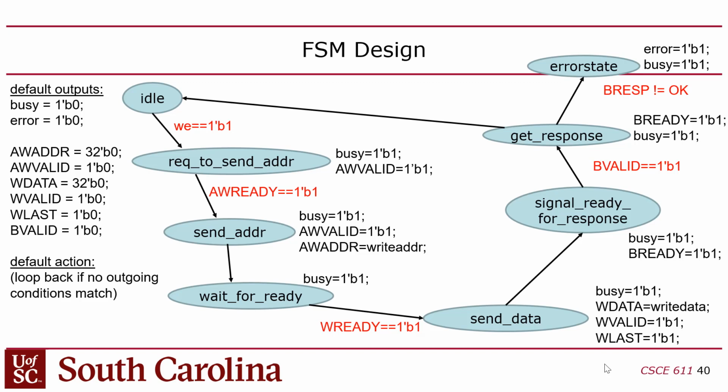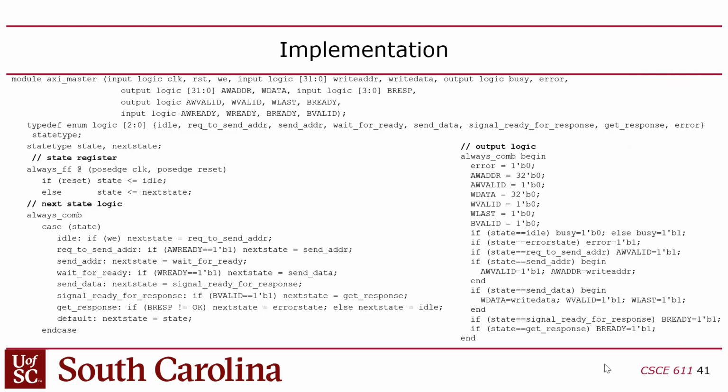Anyway, that's a more practical example. Okay, so then I put the implementation in here, and basically I split it. Again, I've got the enumerated type for the state. I've got the clock logic here, the next state logic here. The next state logic, in this case, I use a case statement. You can use a case statement instead of just an if then else. So I have a case for every state. For the current state, I check the inputs and generate the next state value. Nothing happens to the next state value until I get the next clock edge, at which point it becomes the current state.